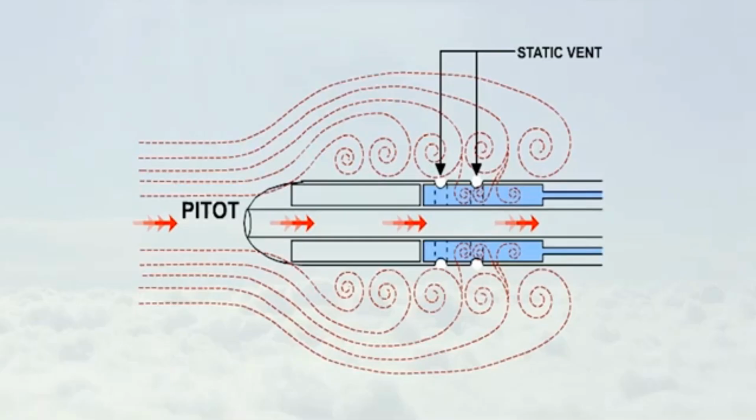We heard earlier that position error is alternatively known as pressure error. Position error arises mainly from the sensing of incorrect static pressure. Position errors throughout the speed range are determined by the aircraft manufacturer during the test flying program for a particular aircraft type. It's not unusual to compile a joint correction card for position and instrument errors and place it in the aircraft near the ASI.